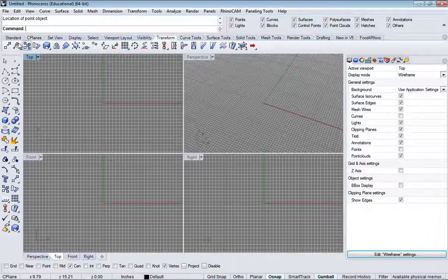Using visibility with layers is also incredibly helpful. The transform tool, we have the set of different transforms, and this is where one of the strengths of Rhino is the ability to modify geometry because of its NURBS nature, its mathematical nature. We can modify it pretty radically without it breaking and doing weird stuff. So here's a whole set of those. Obviously, we have scale. A couple of things about the scale tool is that you can do it as three-dimensional scaling, two-dimensional scaling, or one-dimensional non-linear.